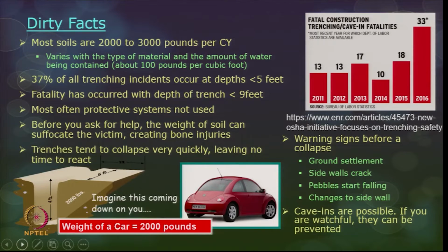Only for shallow trenches, where people take it very easily, a lot of fatalities have happened. Many fatalities happened when the depth of the trench was less than 9 feet itself, not more than that. Most often during these fatalities, protective systems were not in place. That also you should understand.